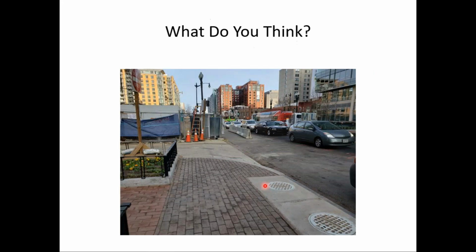Or how about this? Building construction project, sidewalk closed, not really, it needs to be a detectable barricade. The cone can be detected, the cones can be detected, this fence post can be detected, some of these other things can be detected, but the issue is, I'm not sure any of those convey the message that the sidewalk is closed. It may take a while for a visually impaired pedestrian to figure out exactly what's going on there.